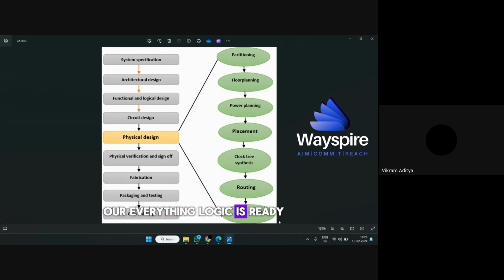Our logic is ready, the code is ready. Till now, the actual physical chipset is not yet designed. So here we are the responsible persons to design the actual physical chipset, using the inputs as RTL or Verilog code, and we'll have some design rule constraints, a set of rules to design, which will be managed by our application department after design and taking inputs from our RTL designers.